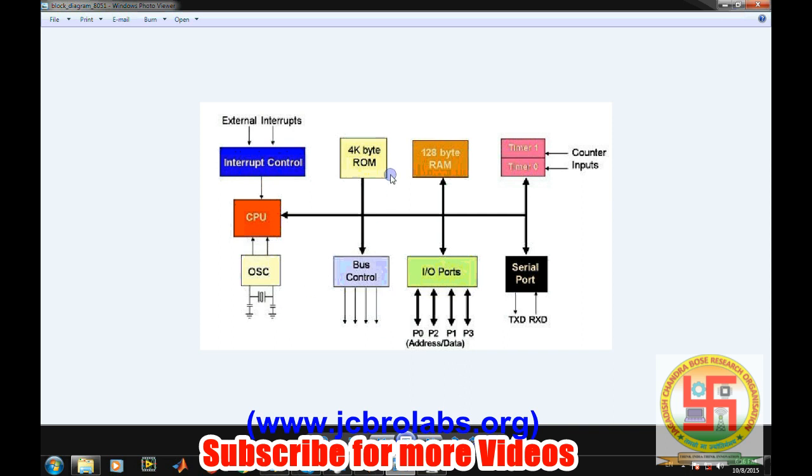And then it has an on-chip ROM. This ROM contains the data memory as well as the program memory. That means the program which you are writing in terms of instructions is written inside this ROM. And also if we are using some specific data, like a table to store some kind of results, we also use this particular memory. Then we have a RAM for the CPU.